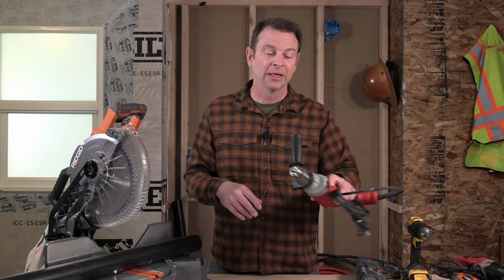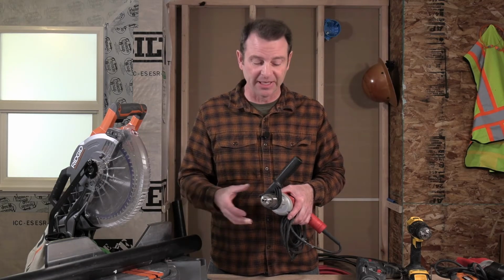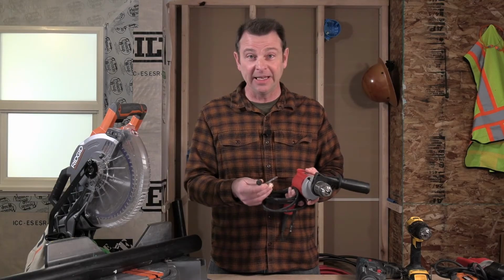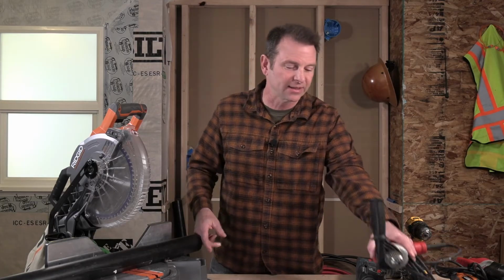On to more drills. I have a whole other series of drills we call hammer drills. Hammer drills work like regular drills, but they can also be set to add a hammering feature to the drilling process. What that does is if we're working with either masonry or concrete, it helps us drill our holes using special bits. This is a simple electric drill with a hammer drill feature. It also has a keyed chuck, which requires a key to make that work. And a lot of this masonry or concrete operation requires a really strong chuck. A lot of times you won't find a keyless chuck on these types of drills.